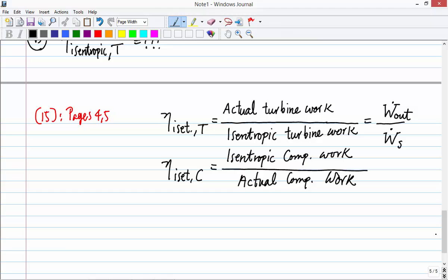So the turbine gives us more work. And we know that something we define as efficiency should be less than 1, for sure, right? The best efficiency is 1, and in a real process, efficiency is less than 1. So in the exam, or when you're solving a problem in thermodynamics or in any other major, first define your ideal world and then judge how the device, which might be a turbine or compressor or anything else, would react. So for a turbine, the isentropic work is more than actual work.